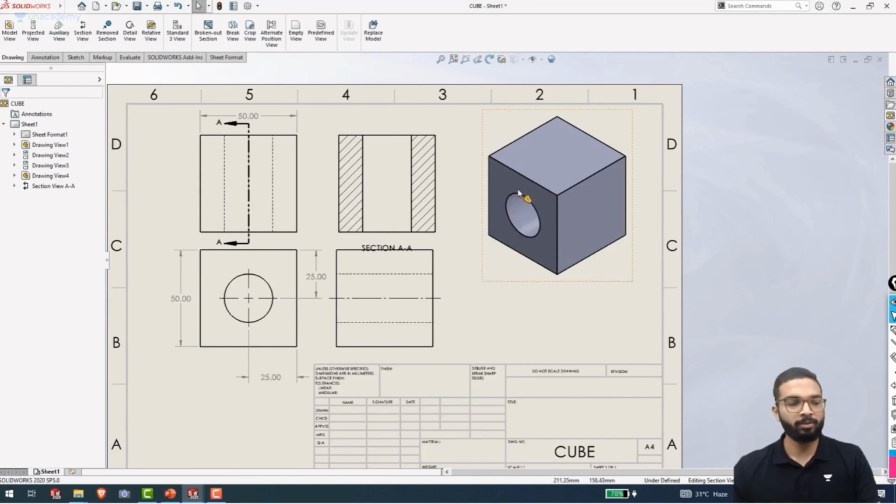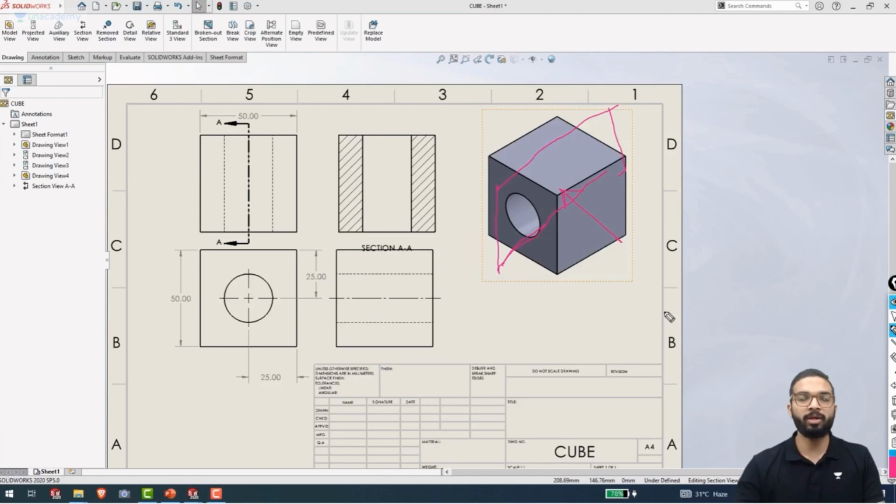What it is doing over here is creating a sectional plane like this. And this body is being cut about this plane over here. And you always get a sectional view normal to the plane that you have used in order to cut it. So when you take a look from the normal direction to this plane, only the faces that were in the same plane as this cutting plane have been shown in hatching, where the faces over here where there is no hatching are the part where there is no material, indicating that there is a hole over here. This is where sectional views come in handy. It shows you internal sections, or rather internal features, wherever you have created the sections.